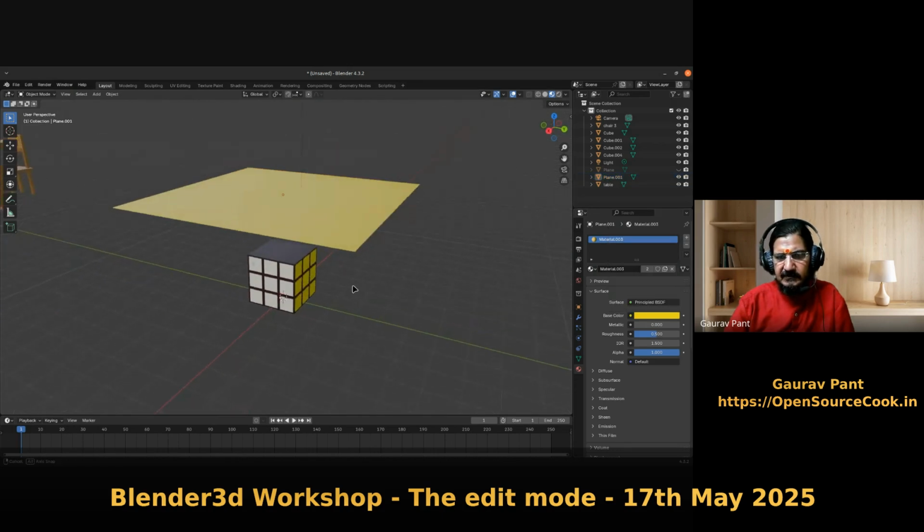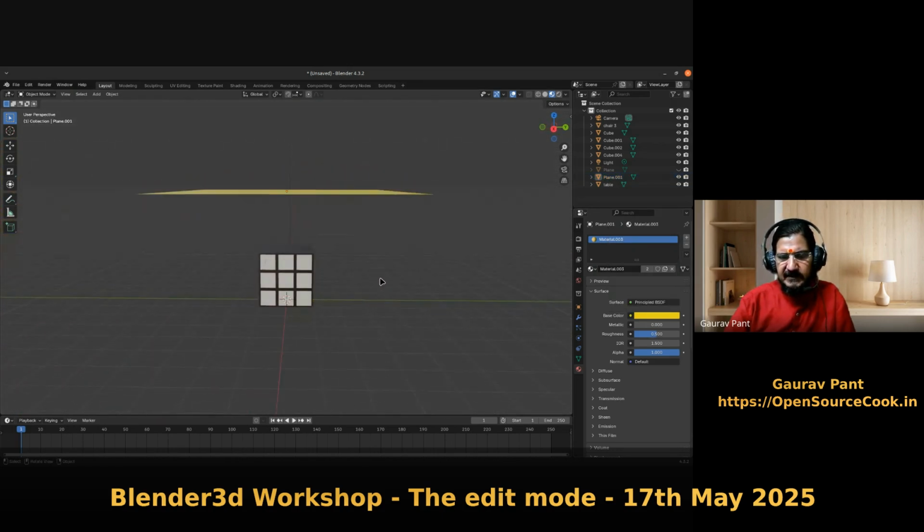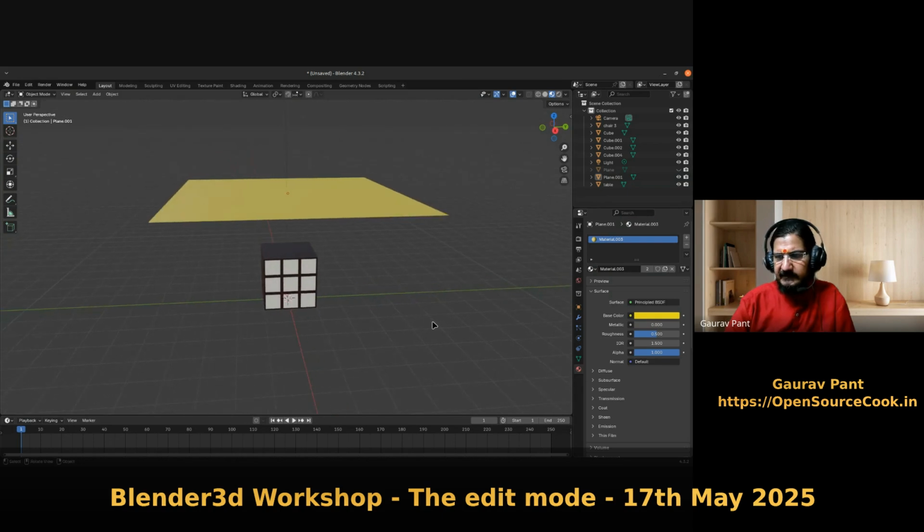Okay, yellowish cloth. So how do we simulate a cloth kind of effect? Fine. Now keep in mind the number of subdivisions decides the fold of the cloth. To do that, Blender has a lot of inbuilt physics mechanisms. So first thing is, we will take the cloth.